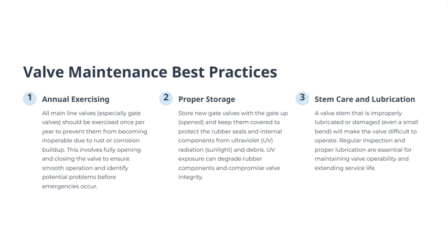Moving on to storage, when storing new gate valves, always keep the gate in the open position. Cover them up to protect the rubber seals and internal parts from UV radiation and debris. Sunlight can degrade those rubber components over time, which can compromise the entire valve's integrity.